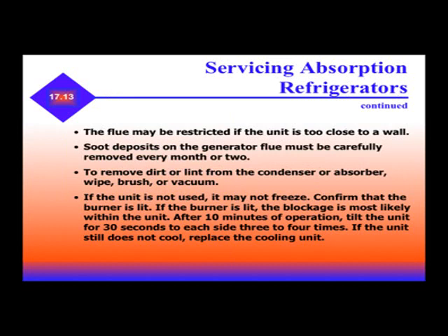If the unit is not used, it may not freeze. Confirm that the burner is lit. If the burner is lit, blockage is most likely within the unit. After 10 minutes of operation, tilt the unit for 30 seconds to each side 3 or 4 times. If the unit does not cool, replace the cooling unit.